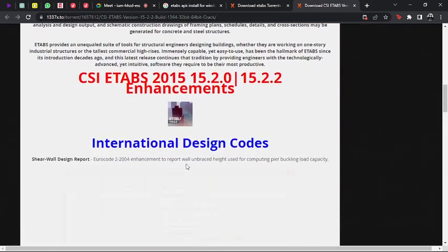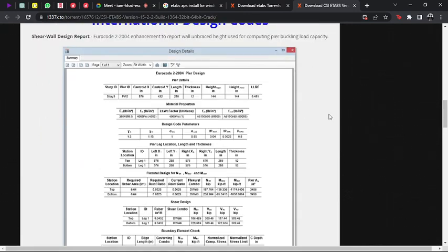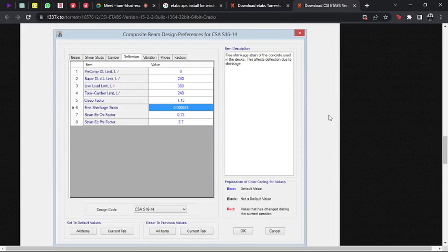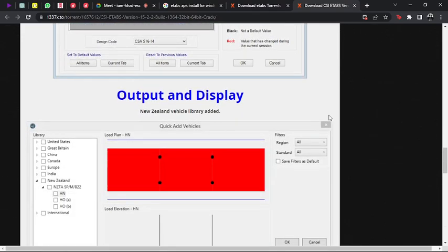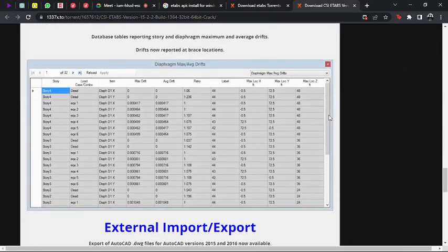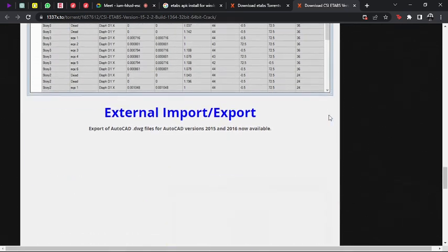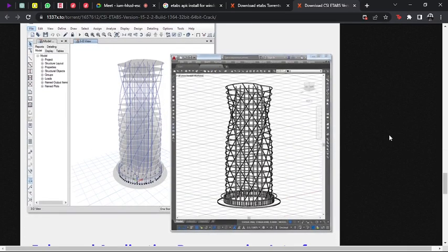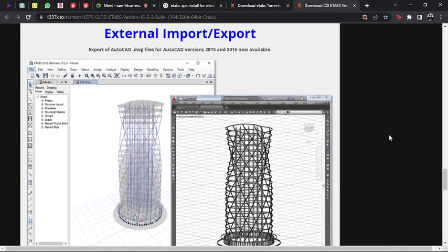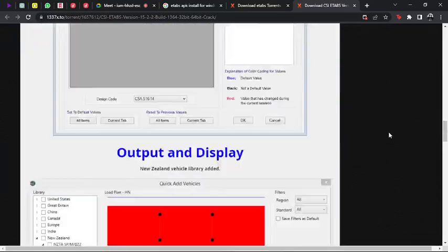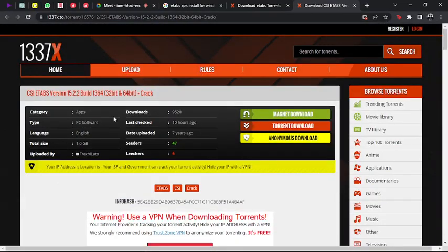Two, now that you have a feel of modeling on a good software like ETABS, you could pull out a hypothetical building with a U shape, for example, same floor area and same height as the rectangular one that we have. So you just rearrange the area so that you have a U shape.